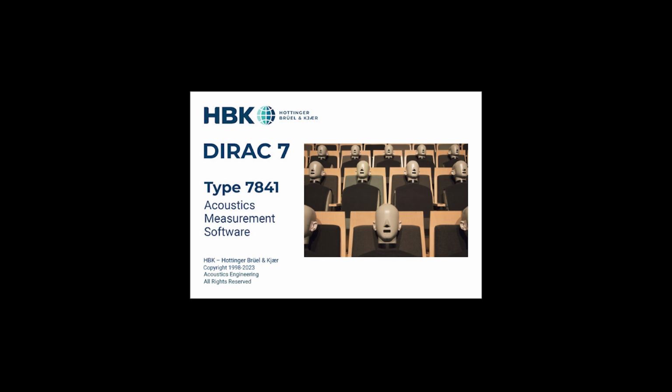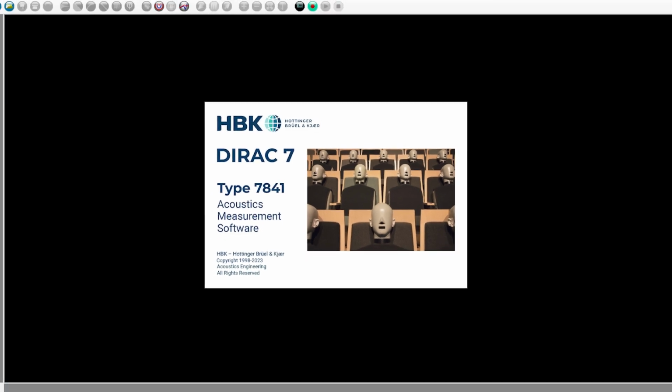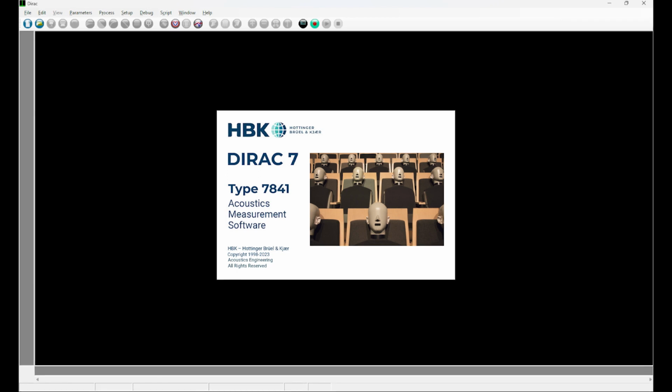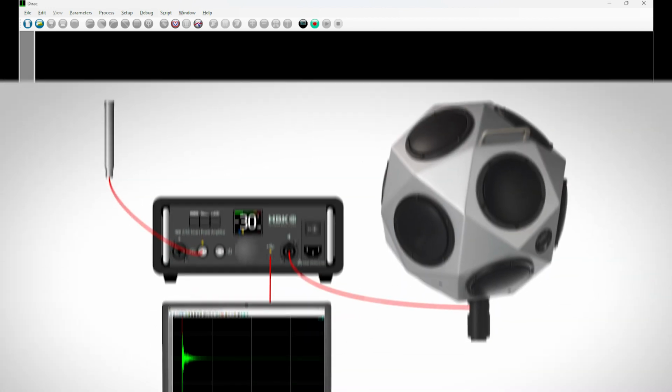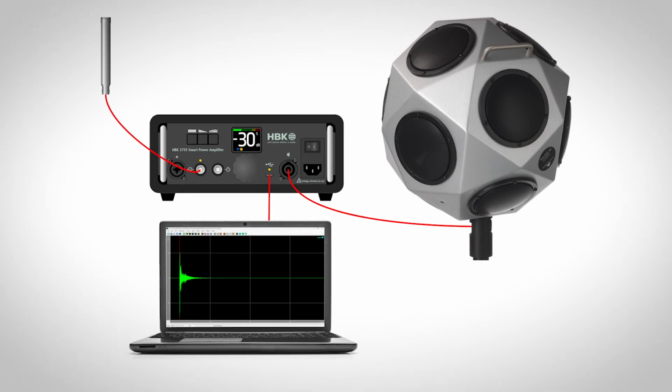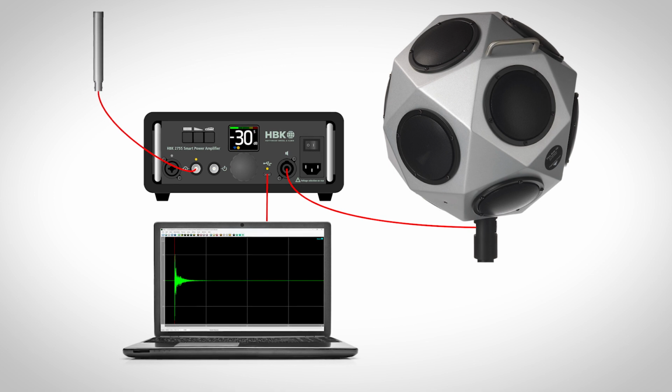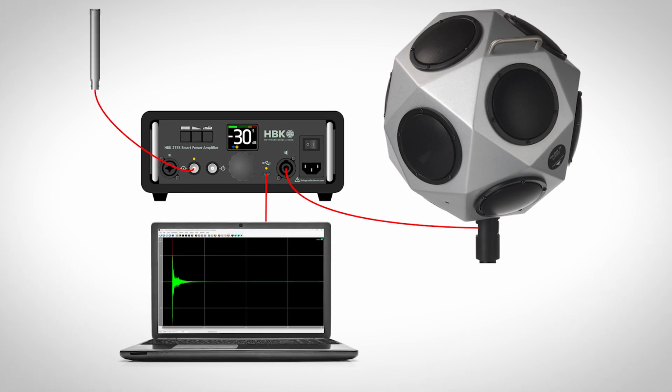This video will demonstrate how to present acoustic parameters measured under various conditions using the project window in Dirac. In this case, we will show the impact of pre-averaging on the impulse response to noise ratio INR and the reverberation time T20.